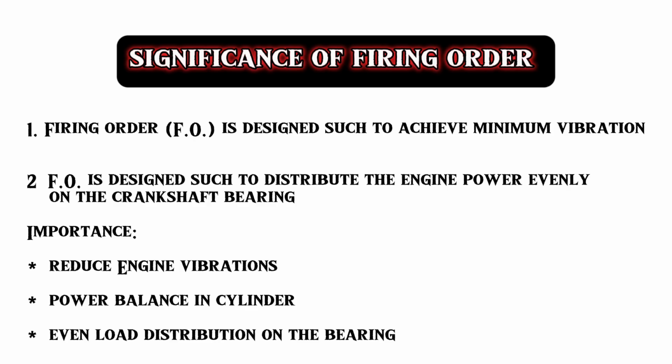Third question, significance of firing order. Firing order is designed to achieve minimum vibration. It is designed to distribute the engine power evenly to the crankshaft bearing. Importance of firing order: reduce the engine vibration, power balance in the cylinder, even load distribution on the bearing.